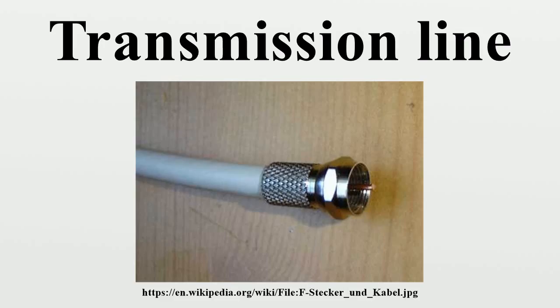For the case of a shorted load, the input impedance is purely imaginary and a periodic function of position and wavelength. Open. For the case of an opened load, the input impedance is once again imaginary and periodic. Step transmission line. A step transmission line is used for broad-range impedance matching.